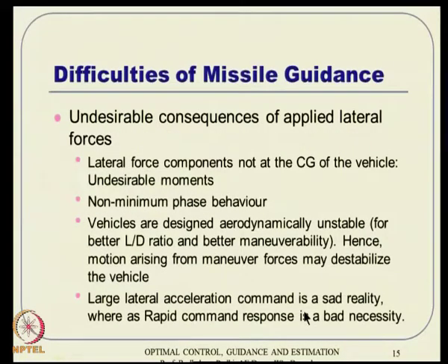There are several undesirable consequences also. Everything does not happen so nicely that we like to see. First of all, lateral force components are not acting at the CG. Obviously there are undesirable moments, and largely they also result in non-minimum phase behavior, especially when you have a tail control vehicle.